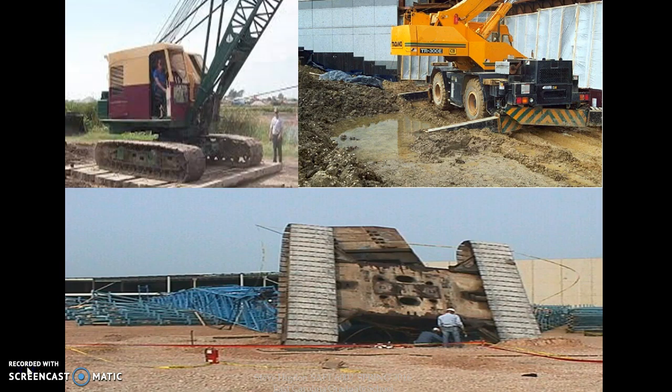Now that you have developed a lift plan and chosen a crane, it's very important that you ensure the stability of where you're going to be setting up the crane. This can be accomplished through grading or mats. It can also be accomplished using steel plate. A crane will fail if it is not set up properly on a firm, level surface.